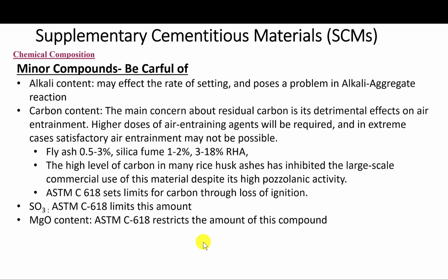We sometimes have specially designed furnaces to completely remove residual carbon from decomposing cellulose, in that case at a low enough temperature so that the amorphous silica will not crystallize. That's again another aspect that you have to be aware of.